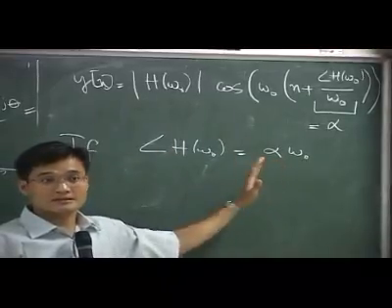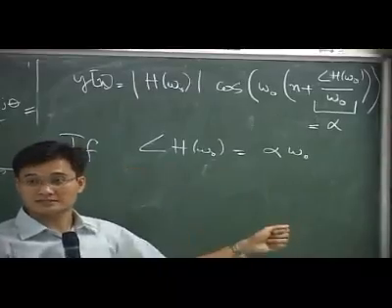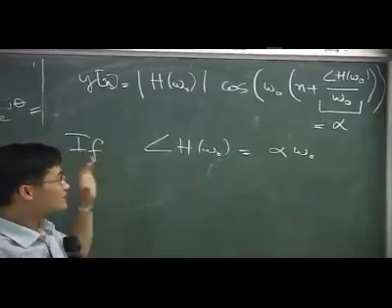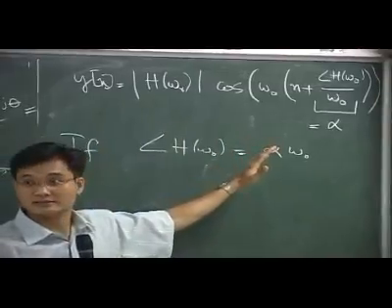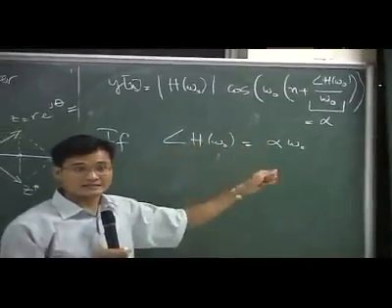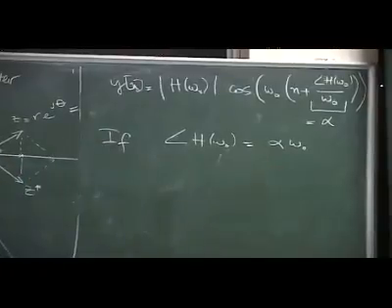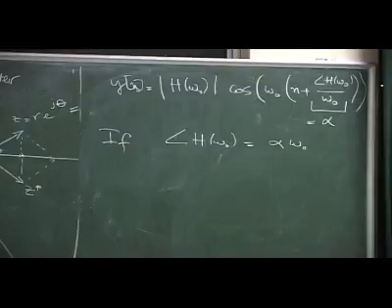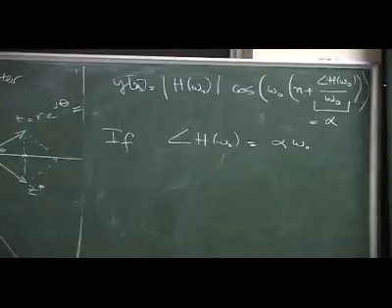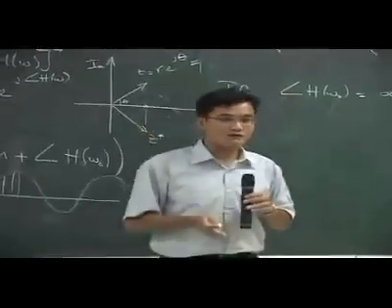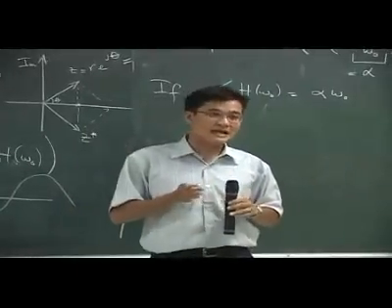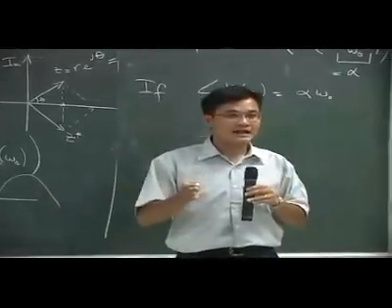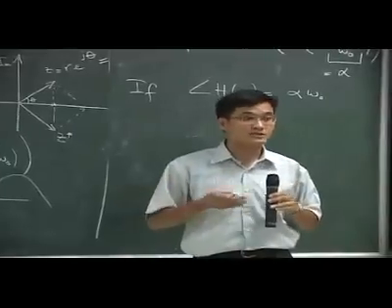Right? Now what happens if that's not the case? If that is not the case, then different frequencies get shifted differently. And that would be very bad, because let's say I play music here, boom, boom, boom, boom, with different frequencies playing at different times. I pass it through a filter, a really good filter design. I go over here, and now the different booms in different frequencies are all mixed up, and you get very distorted music.